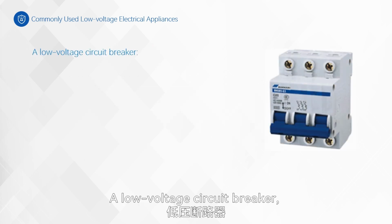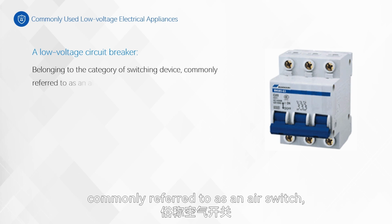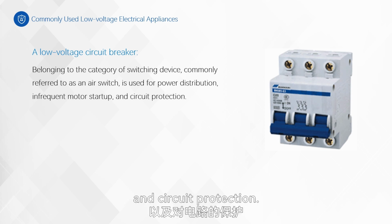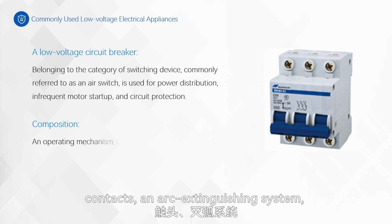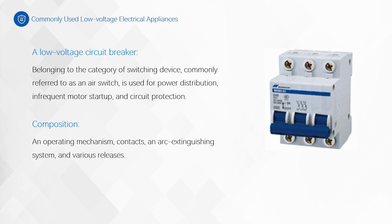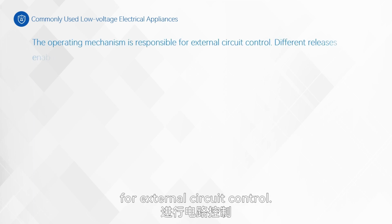A low-voltage circuit breaker, belonging to the category of switching devices, commonly referred to as an air switch, is used for power distribution, infrequent motor startup, and circuit protection. These breakers consist of an operating mechanism, contacts, an arc extinguishing system, and various releases. The operating mechanism is responsible for external circuit control.